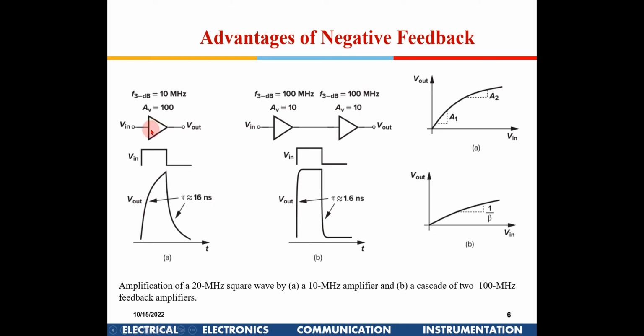There is one more aspect to it. When I'm designing this amplifier, I am operating it at a particular operating point, but if I give such a large input signal, the operating point, the Q point, which we saw in the DC operating conditions, gets disturbed. Generally some transistor will come out of saturation and the gain will drop. So you will have non-linearity like this. For a certain region it is linear, and then slowly the gain drops. That will also cause distortion in the output waveform.